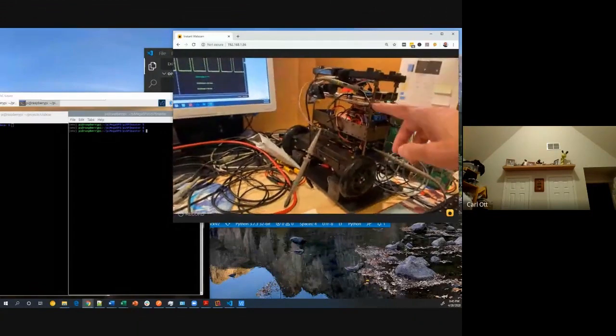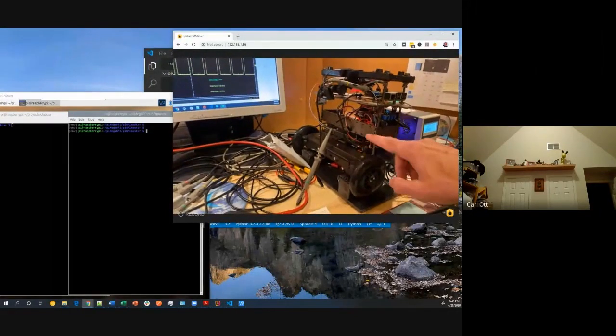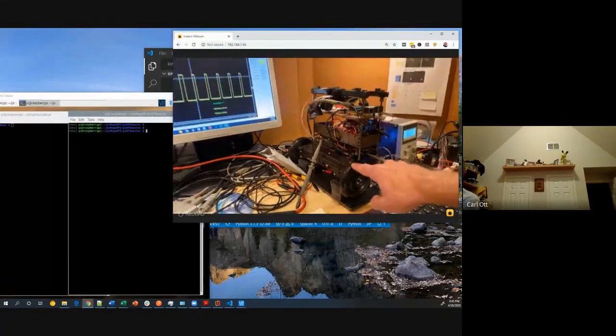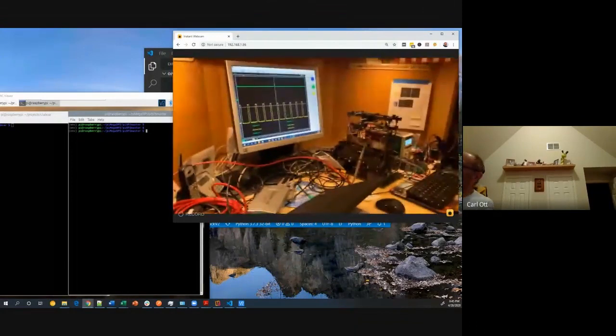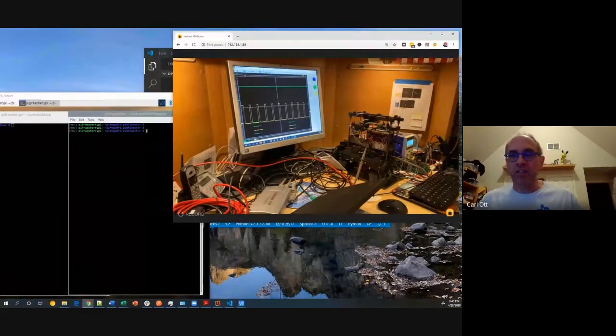The concept is that I would use the lower part like a traditional DPRG robot, but then I would have an SPI interface to the Raspberry Pi. The Raspberry Pi is the master, the Arduino is the slave. So I think this is roughly what I showed last week. On the bottom, every time the yellow trace is high, my 20 millisecond loop is active. It gets a little wider about once a second because I do a few extra console writes. The top line is whenever the Raspberry Pi initiates a SPI transfer. I have this custom protocol I wrote that moves about 19 bytes, 16 of them payload.